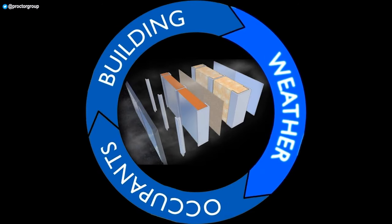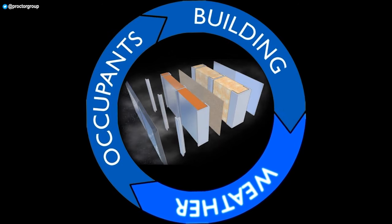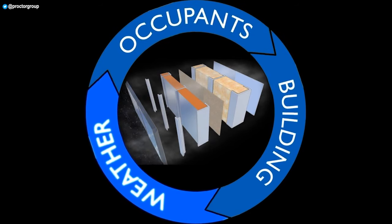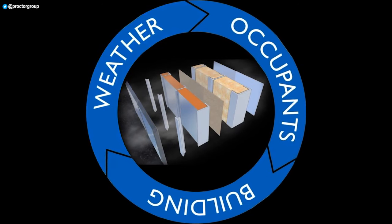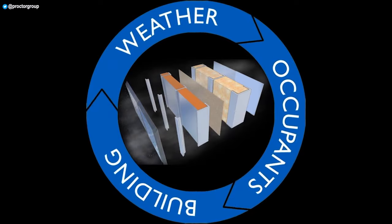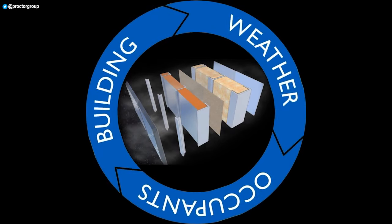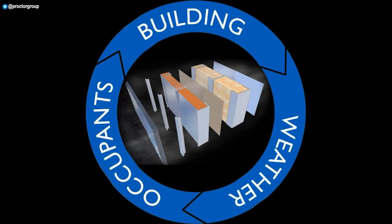Lastly, designers should consider the effects of the external climate, which, being site-related, is beyond direct control, but may be moderated by the building's form and orientation in relation to topography, prevailing winds, sunlight, and overshadowing. Moisture and condensation can lead to mould and bacteria growth, which, if left uncontrolled, can have a significant impact not only on the fabric of the building, but also on the health and safety of its occupants.